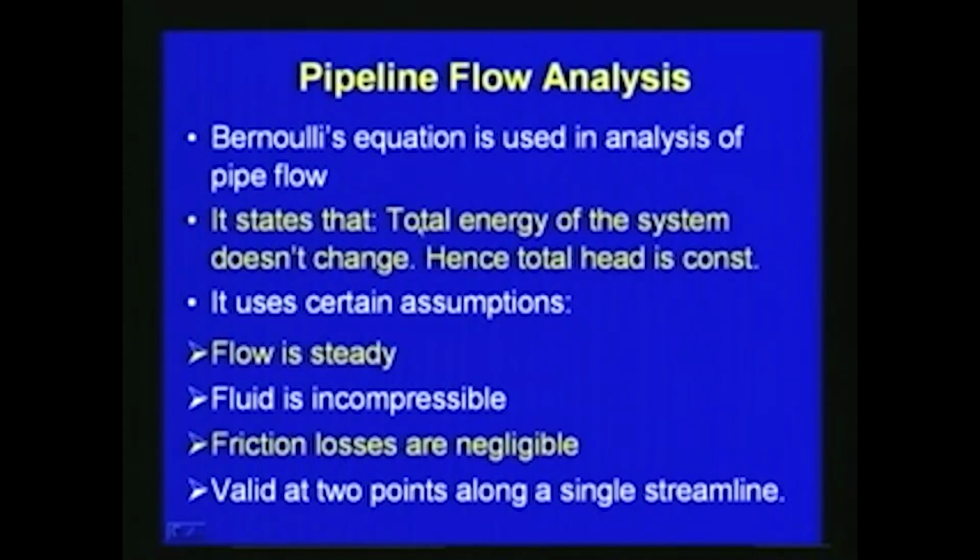Then we can see which approach we have to utilize, whether we have to go for an iterative procedure or whether the solution is straightforward. Generally, for pipeline flow analysis, we can use the Bernoulli's equation, and as we discussed earlier, the Bernoulli's equation states that the total energy of the system doesn't change, hence total head is constant. So, when we design a pipe, for example,